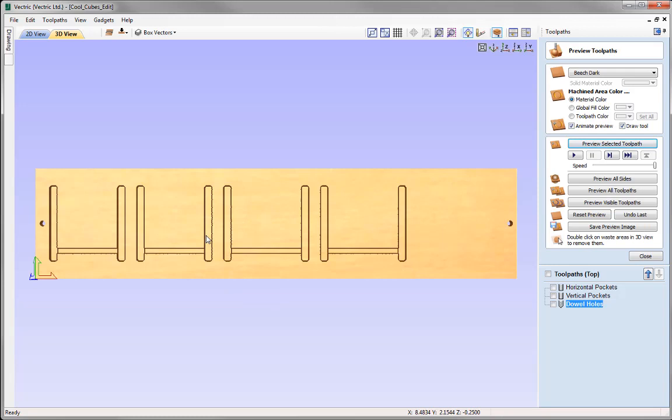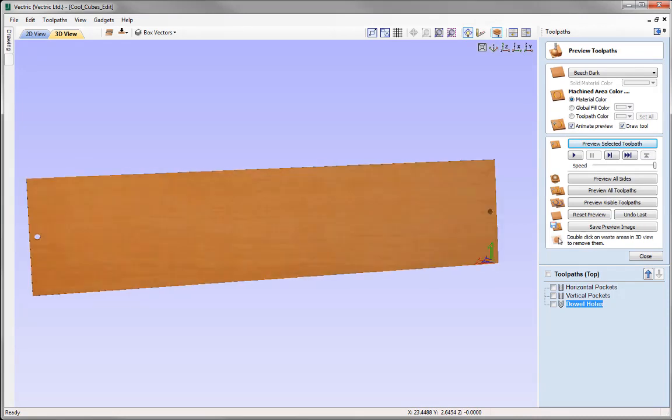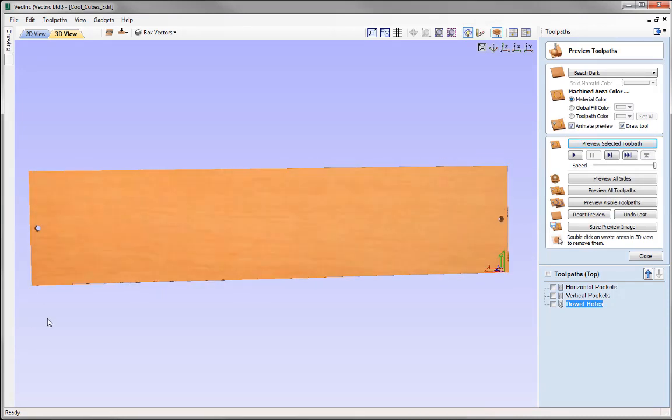So at this stage, what we'd do is we'd then take our material off of the material bed, and then we'll insert the dowels into the spoil board, and then we're going to take our material and we're just going to flip that over along the x-axis like this. We'd align it to the dowels and secure it in place, and that way we know that our x, y, 0 coordinates are going to be aligned with each other. And then we'll just look at running the other toolpaths.